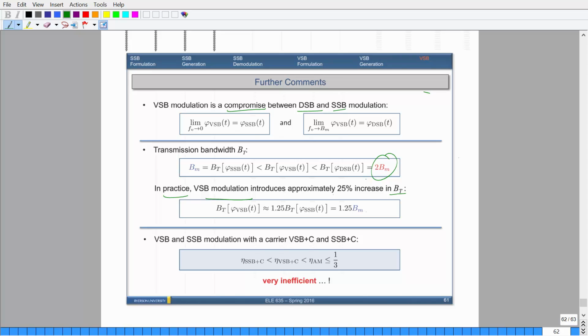Okay? So if you did vestigial sideband modulation with a carrier, right, so single sideband with a carrier, if you decided to add a carrier, so this is for, let's see, envelope detector, I guess. So you don't have to use coherent techniques. You can certainly use an envelope detector if you wish. But if you decide to add a carrier on top, you're still going to get very bad efficiency.